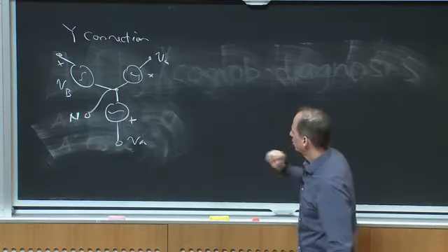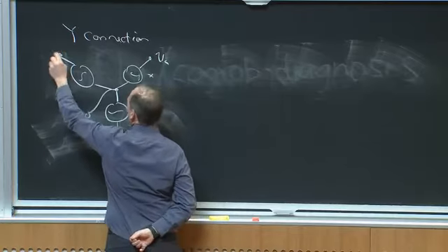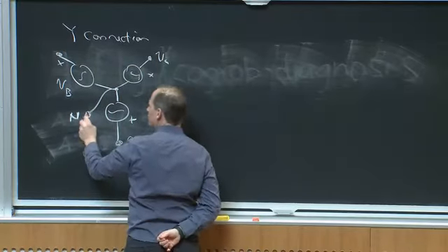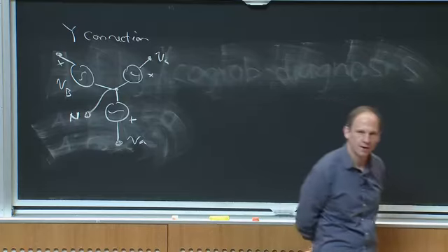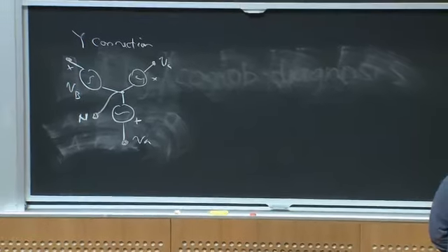And then I have 3 voltages that I can play with, each with respect to this neutral voltage. Something where I brought out this wire, and this wire, my 3-phase voltages and the neutral, would be called 3-phase 4-wire. And that's a very common way to connect a source. You can also connect a load that way, and we'll talk about why.